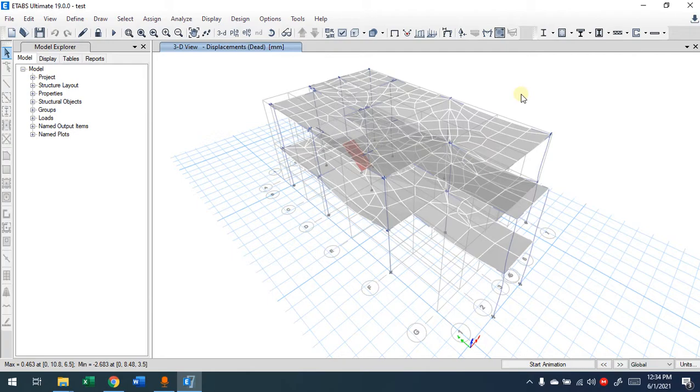In the finite element method, the design of slab will be different than the column strip and middle strip. I will show you an example for the middle strip, the one that you do in reinforced concrete, that if you use middle strip, column strip, you will see the top bars, bottom bars. But in here, in the finite element method, we're not going to see this one. We'll see it as a total area, for example, area required per meter square in the design of slab.